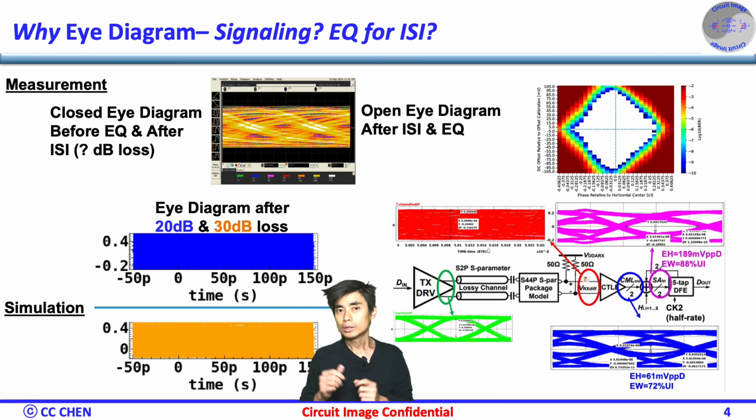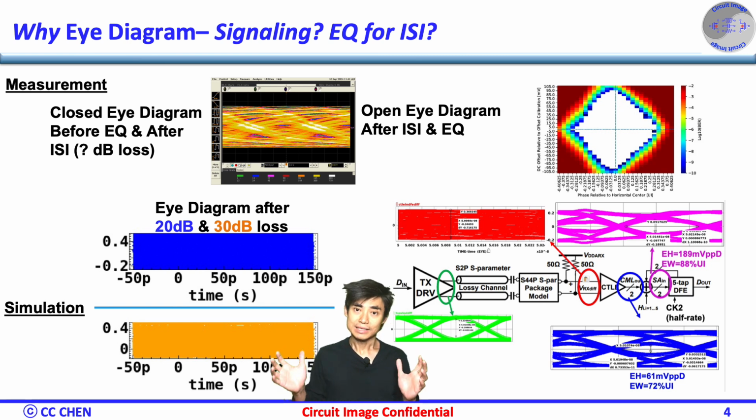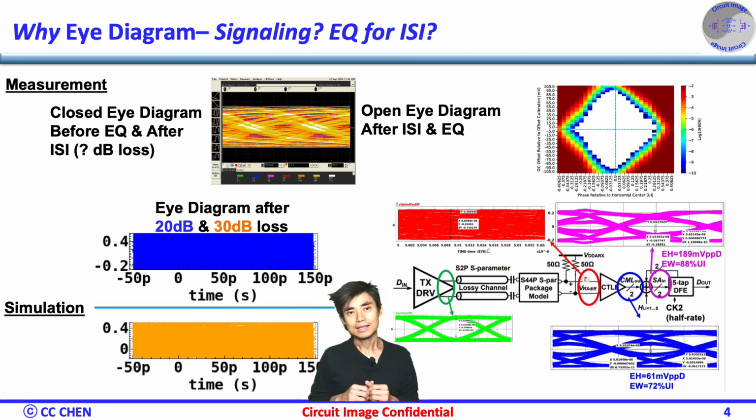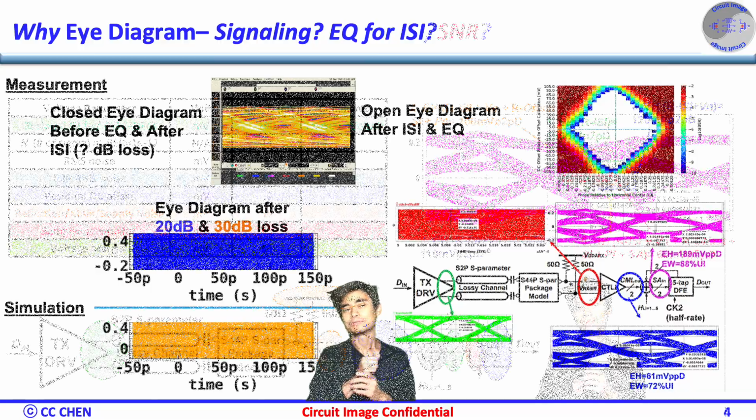So, during the design iterations, you can optimize your EQ design by looking at different eye performance in eye width and eye height margin. Since there is no perfect EQ to recover the exact eye opening before the channel, the designer should check different eyes and decide which version would be the final satisfied EQ design as the final tape-out sign-off.